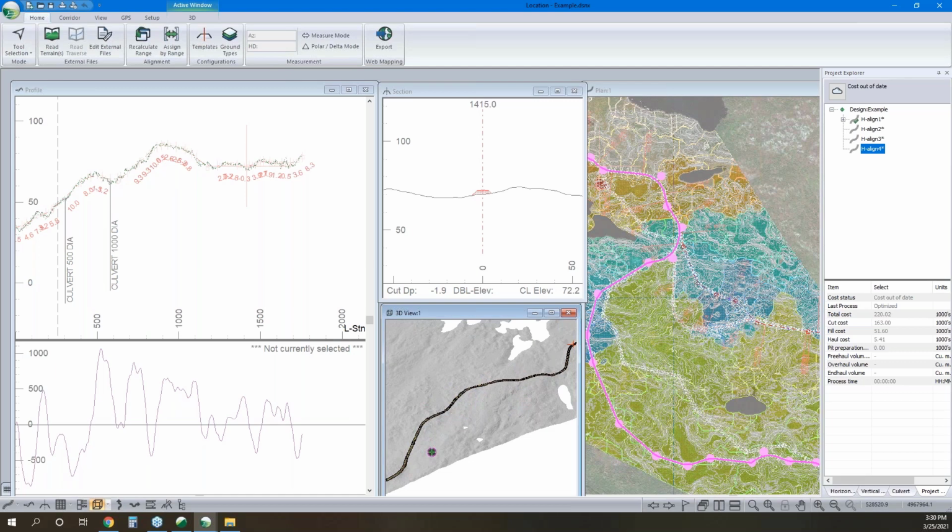All right, so let's dig into some of these questions. Any thoughts on minimum accuracy for data? That will depend a lot on the project at hand and how tight you want control when you're constructing it. That's up to the designer to decide, and as mentioned when we talked about our different sources, a lot of the time you'll be able to find a LiDAR report for those sources, even if it comes from publicly available data, which will give the accuracy limitations in it.